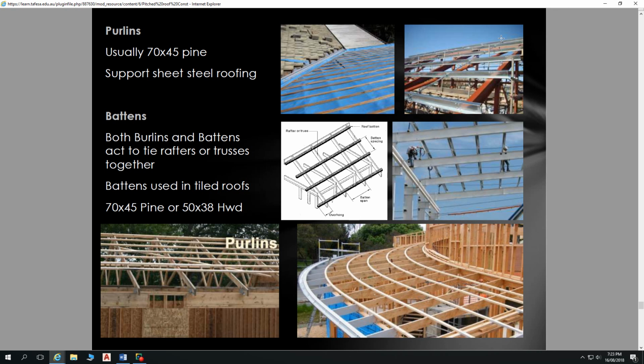These will be our Z purlins happening here like that. Our Z purlins are really handy because you can get a tech driver in here and fix that down. If that's a C purlin that carries over the top like this, you're restricted. So that's essentially why we use Z purlins, and that's it. Easy to fix, and then we fix our sheeting to this here, like that.